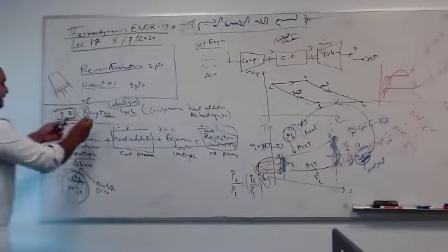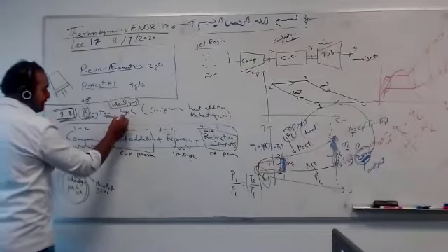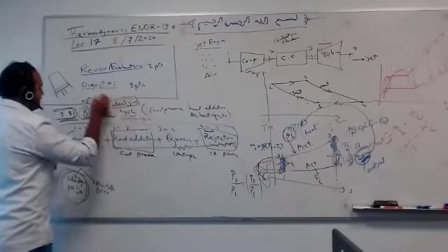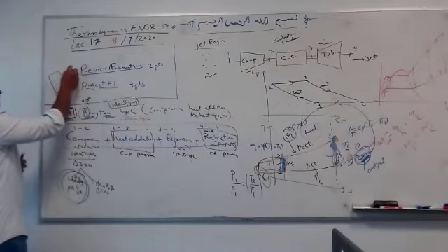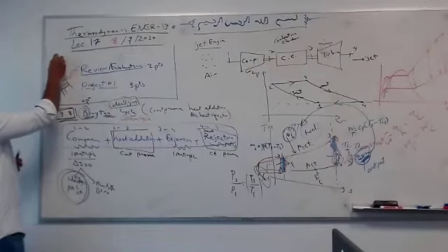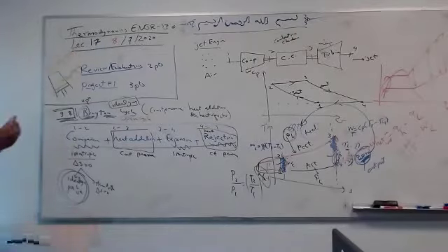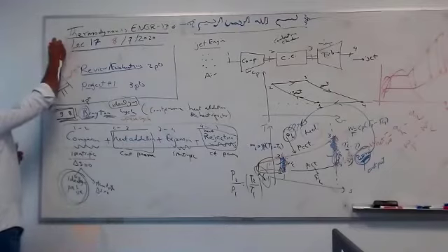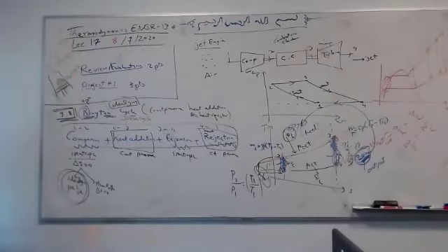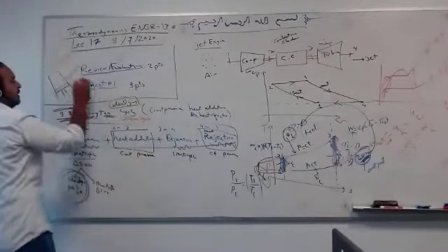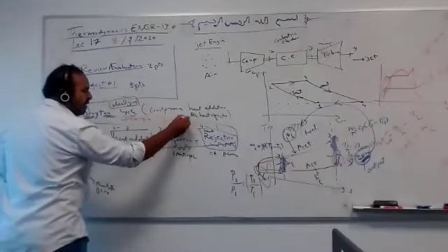Anyway, the Brayton cycle is an open cycle, unlike the others, which are closed cycles. For a closed cycle, Q minus W equals delta U. Do you remember this, guys? And if it is constant pressure only, like the heat addition in a diesel engine, we can say Q equals delta H. Here, everything is open. Forget about this law. Q minus W equals delta H.